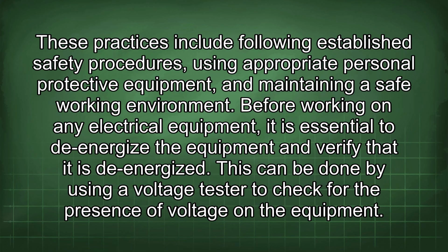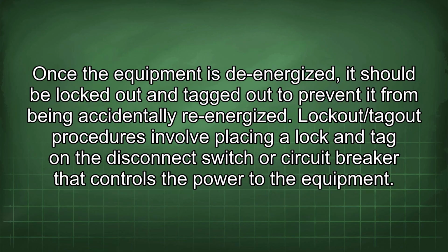This can be done by using a voltage tester to check for the presence of voltage on the equipment. Once the equipment is de-energized, it should be locked out and tagged out to prevent it from being accidentally re-energized.